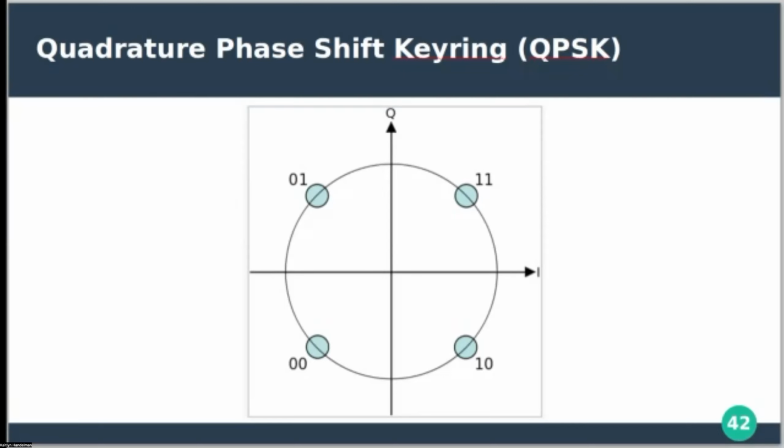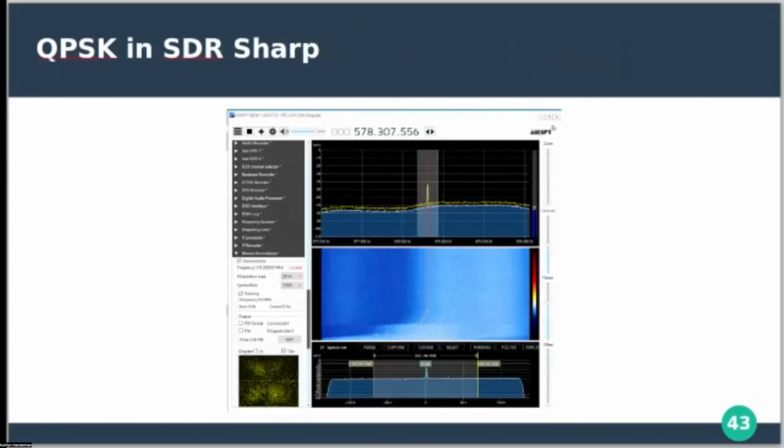And by the way, how you figure out where I and Q go is purely in their phase. This is why so many digital electronics use phase modulation. The SDRs down mix the signal, and then you can get this nice graph to encode data. And like I said, every digital transmission uses this. Your Wi-Fi, your cell phone, all of them. This is how data is transmitted over wireless signals.